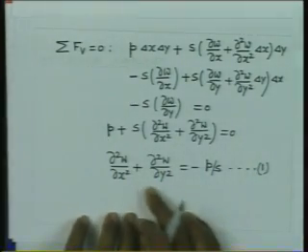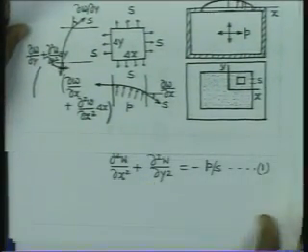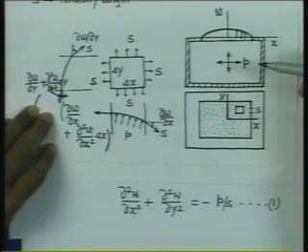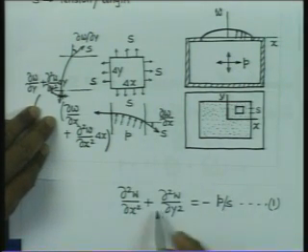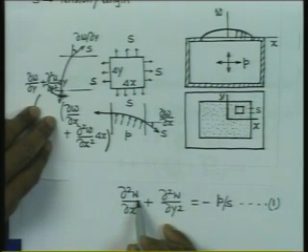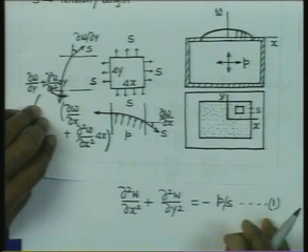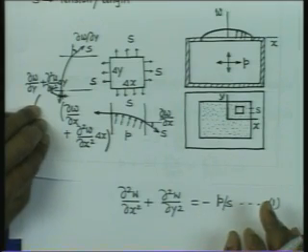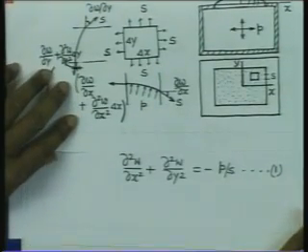So, therefore, the deflection of the membrane that we were looking into, the deflection of the membrane under pressure, you are going to have the deflection satisfying the function w, which stands for deflection, is going to satisfy the Laplace equation, because P is a constant, so also S, which is the tension per unit length along the boundary, is also constant. Therefore, this is going to be the equation satisfied, and it is a Poisson type equation.